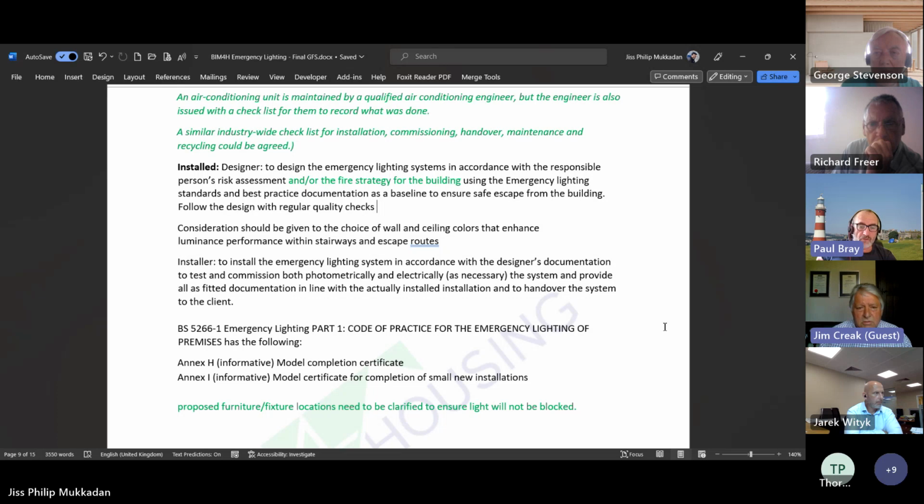Yeah, but my point that I was trying to make earlier is that if we're at the risk assessment stage of deciding that the emergency light system needs to be installed, something's been missed along the line, because it should either already be there, or there's been a change in the standards, or you're doing a refurb of the building, so you're reviewing it. You wouldn't ordinarily retrospectively install emergency lighting in a building unless it has been identified from a health and safety reason or a fire risk assessment process. But you rarely retrospectively install systems to meet current standards. It's not a given thing.